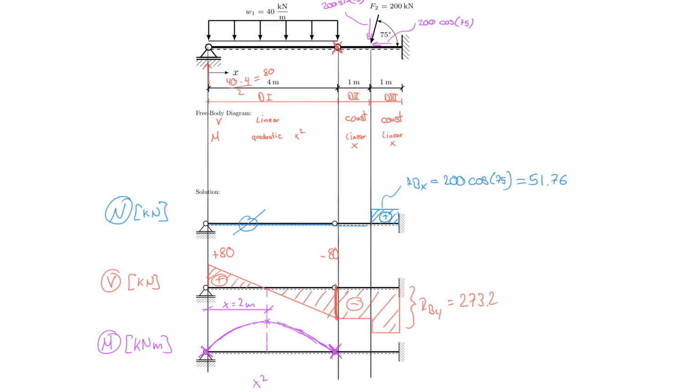And so now you see that at this location here, pretty much at the continuation from the linear slope to the constant, they have the same value. What that means is that here in the moment diagram on the left side, the tangent is identical to the tangent on the right side here. And so I can therefore, not that my hand drawing can really show this, continue that tangent which goes down, and so ideally that matches my parabola there.